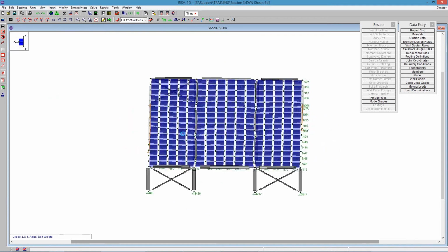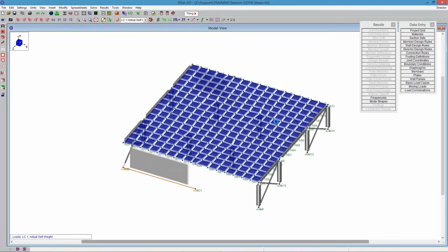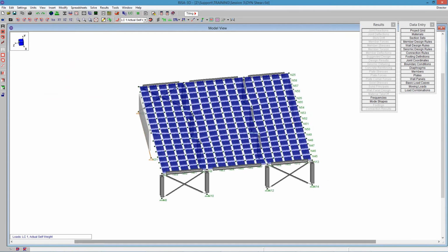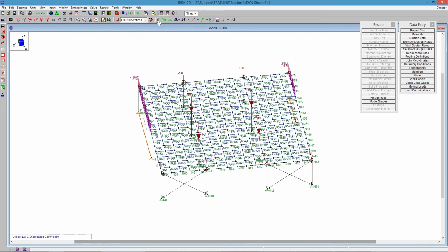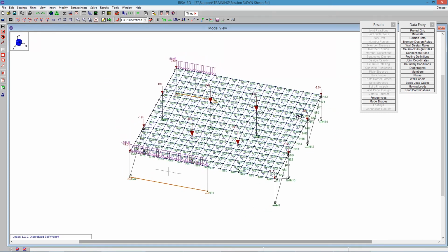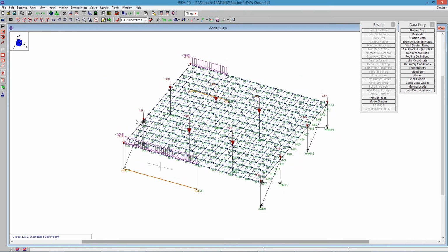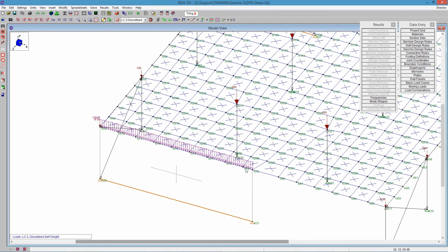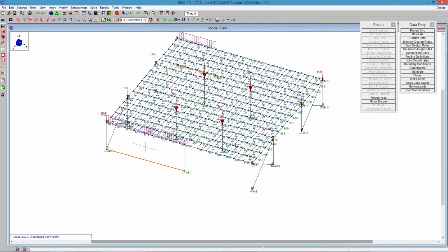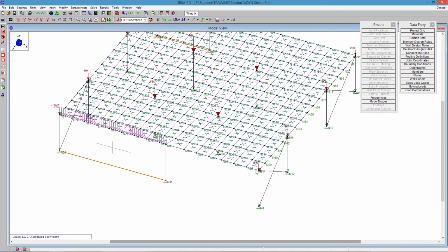So what do we do to fix that? One way you can do this is what I said, discretizing the mass. Instead of using just that self-weight, we can actually apply the self-weight manually to the structure. If you look at this, what I've done here, I'm going to go back out of that, is that at every point you would calculate the mass of that structure and then reapply it manually. The weight of the wall is going to be applied as a line load. Any beams that are framing in or columns, you can take that as point loads that you would apply directly on top of the columns.